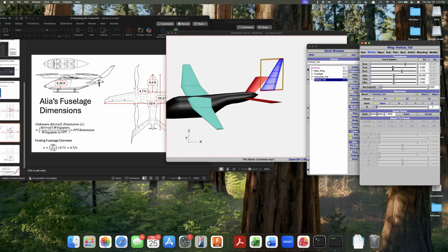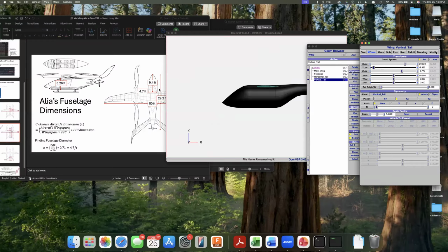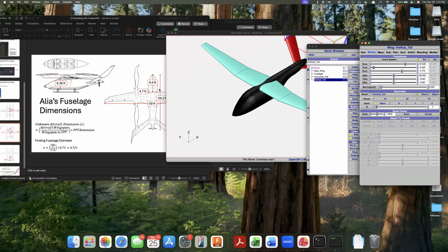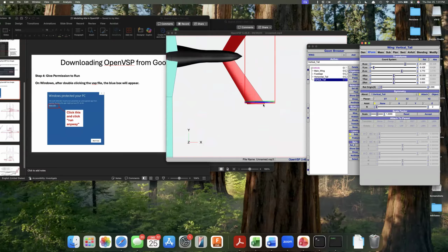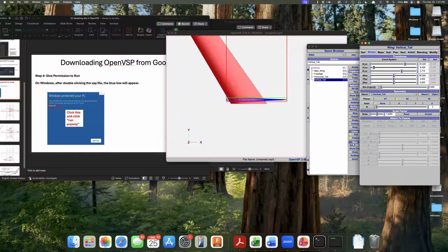But we also want to separate the two wings because they both will act as vertical tail. So for that, we change this y location. You see the y location, right? So we change it until we get to the right orientation of the wing. So I'm going to change this until I match up with the edge of the horizontal tail. Excellent, right? That looks pretty close.